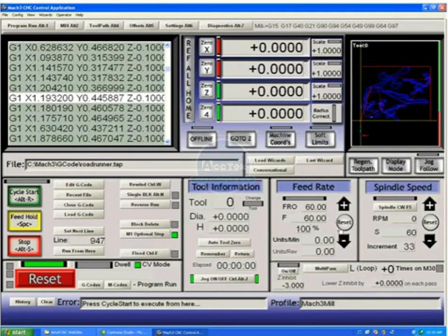We have a feed rate selector. This is feed rate override. We have units per minute and units per rev that are real-time updates as you're moving. Here we have our spindle speed selection. We can turn a spindle on or off. We have spindle speed override, that we can override the spindle speed that was set in the G-code program and allow the spindle to speed up or slow down. Pressing reset will of course bring it back to 0.